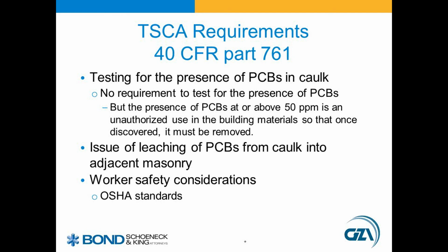But there is a requirement that if PCBs are found in those materials at or above 50 parts per million, it's considered to be an unauthorized use in the building materials, so that once you discover it, it must be removed. Also a concern is the leaching of the PCBs in the caulk into adjacent masonry. And anyone then dealing with removal of the caulk and that adjacent masonry, there are certain worker safety considerations and OSHA standards that have to be addressed.